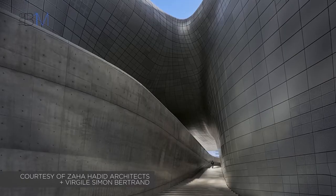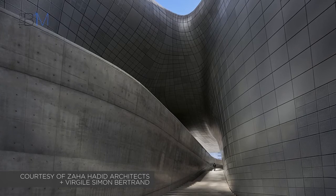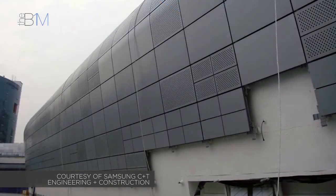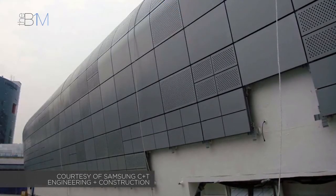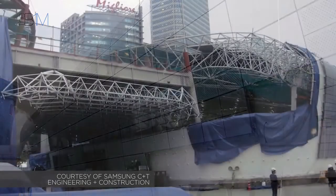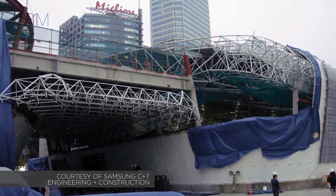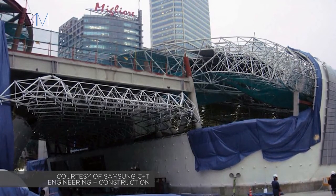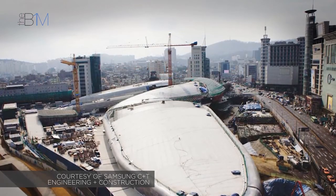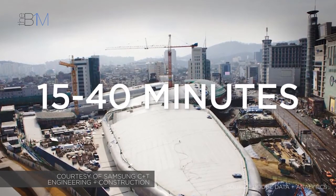To construct the building's facade, the project team looked for a quick and affordable way of manufacturing the 45,000 aluminium panels. As each panel was unique, a way to mass customise panels without using fixed moulds was required. Sheet metal processing technologies considered at the start of the project could only deliver panels at a rate of 1 every 2 hours and at a cost of $7,000 per square metre. Eventually, the team developed a new hybrid sheet metal processing technology called multi-point stretch forming. The data determining the form of each panel was extracted from the building information models. Fabrication costs and timescales varied dramatically with each panel, but averaged between $250 to $400 each. The average fabrication time ranged from 15 to 40 minutes.